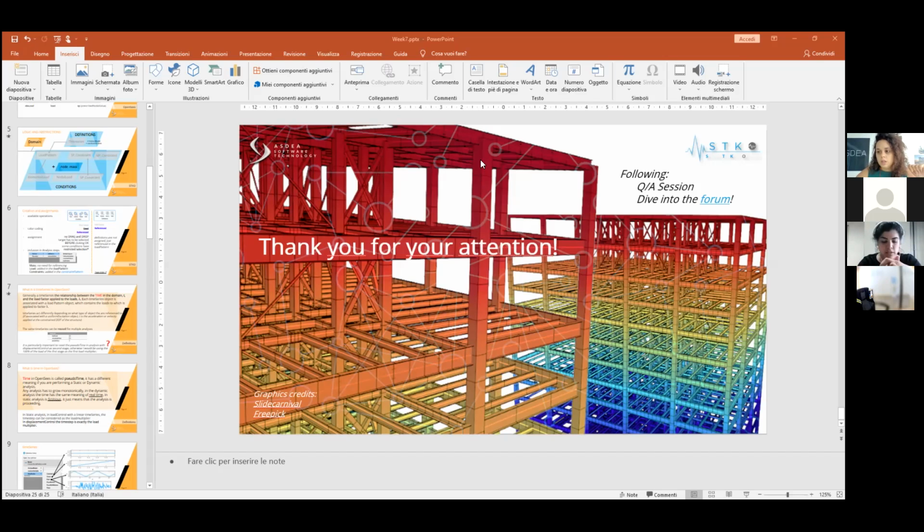We only leave this constant load check with the pseudo time reset if we are interested in having the last stage of the first stage constant for the second one. But do not mix them up, because you can do this and not reset the time step. I don't see when you would want to do this, but anyway, these are two different concepts.